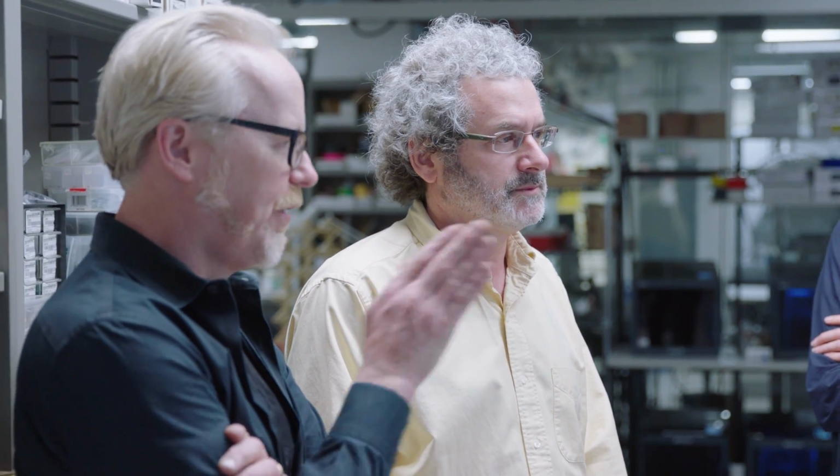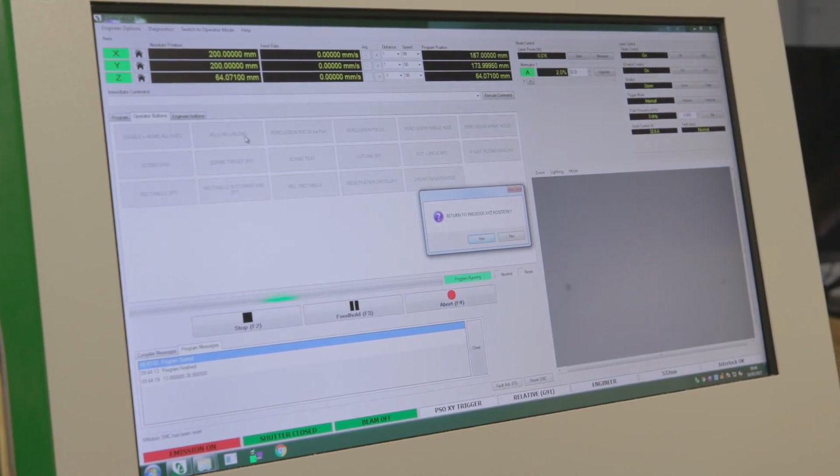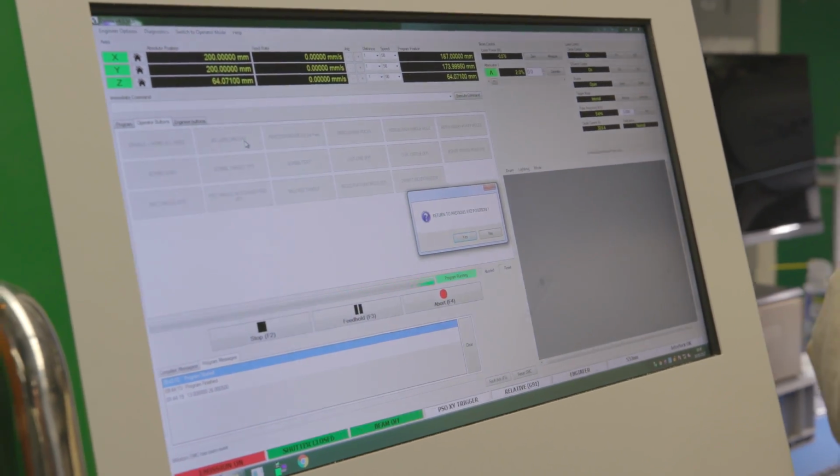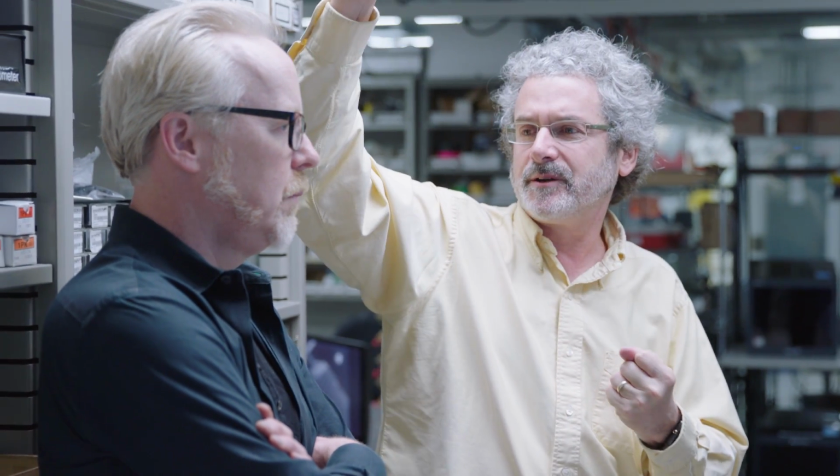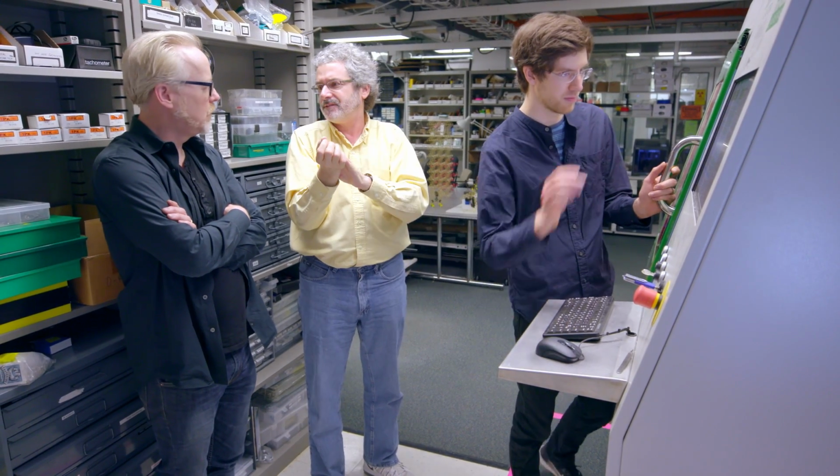This will be the Lego, and this is clearly not the smallest size you're going to go for. So there's different sizes for different purposes. This one is about a 20 micron curve. In the back, as we go by, I'll show you, we have an even crazier one of these, which is a diode pump solid state laser. We have a femtosecond laser, so the pulses are just a few cycles of light long. But the power during that pulse is 600 megawatts. And that's enough to rip the material apart to make micron scale features.